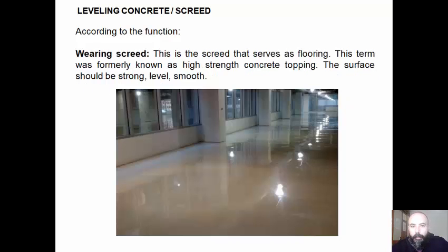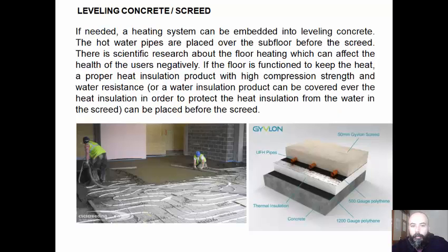Or we can have wearing screed. This is the screed that serves as a flooring. This term was formerly known as high-strength concrete topping. The surface should be strong, level, smooth. If needed, a heating system can be embedded into leveling concrete.